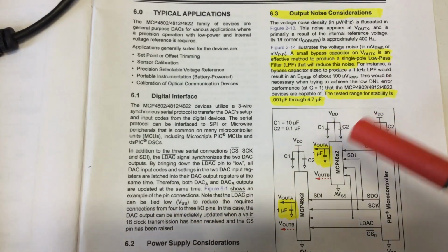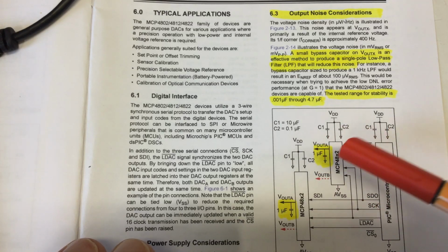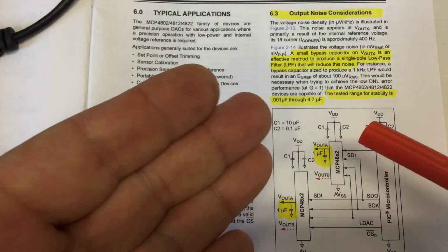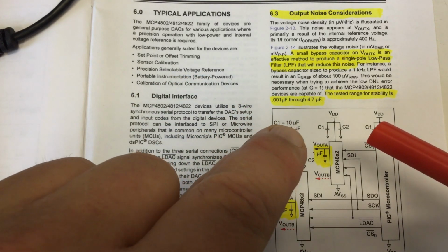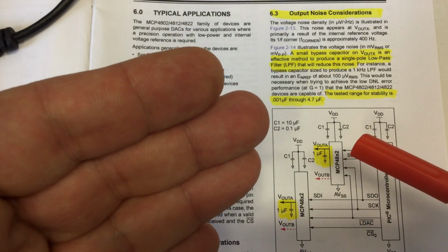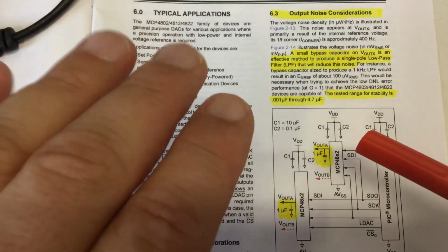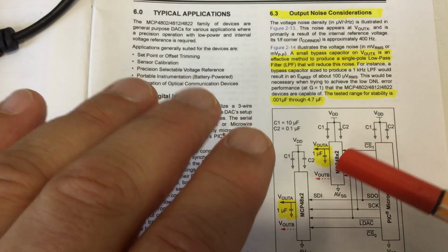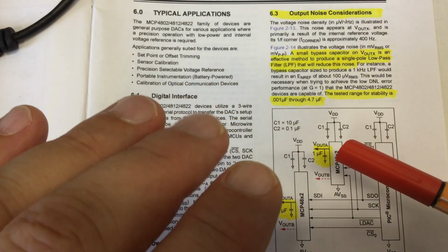Let's just forget about these filter bypass capacitors directly connected to the outputs of the DACs. At least in my application scenario, where there's just an oscilloscope probe with 10 megaohms impedance connected, they simply don't work. There might be other application scenarios where they do their job, but somehow I doubt that.